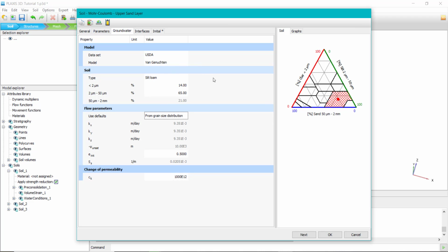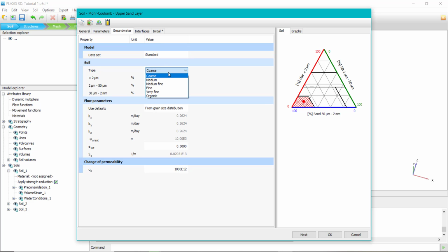Okay, the combination of guideline, model, and type of soil can lead you to the water conductivity parameter, and you can assign it within a seepage analysis during your main analysis. Okay, just forget about this. I don't have any seepage analysis in this simple model, so leave it like this.